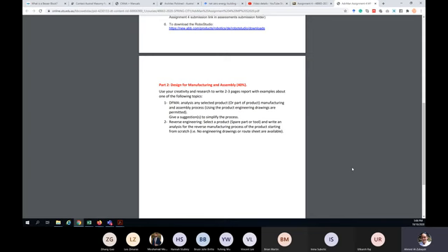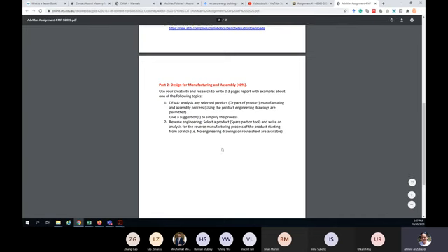Also, you can talk about reverse engineering, where you select a product, for example a spare part or tool, and write down an analysis for the reverse manufacturing process of the product, starting from scratch. So in this case, no engineering drawings or raw sheet would be available. You can simply start with a part, and either do the measurement for it using the CMM, getting all the dimensions, creating the CAD model, fixing it, and doing the CAD/CAM operation and machining. Or you can simply do 3D scanning of the part, get the CAD model, process the CAD model, and then do the CAD/CAM operation for it, 3D print it or machine it. So these are some of the suggestions we can have for the second operation.